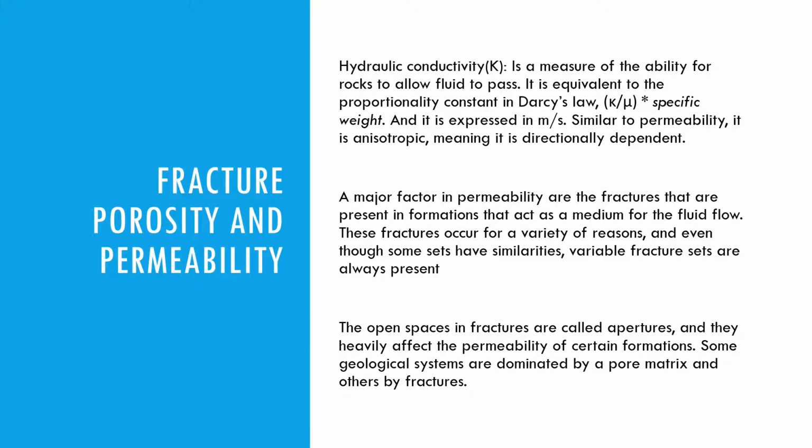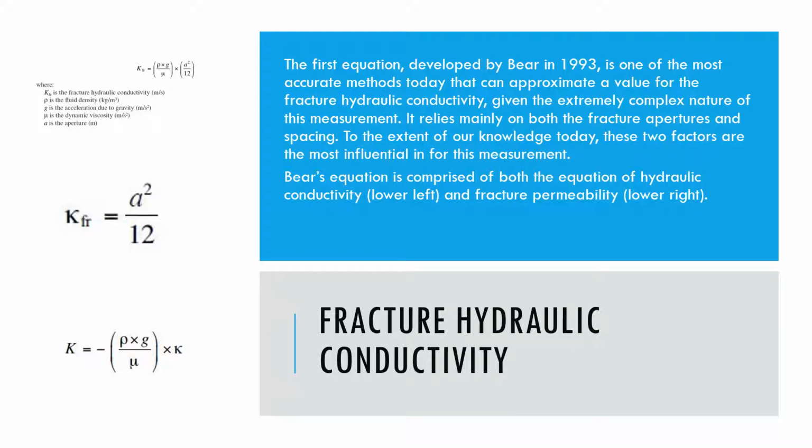The open spaces in fractures are called apertures, and they heavily affect the permeability of certain formations, and by certain formations I mean formations that are fracture dominated rather than matrix dominated. Some geological systems are dominated by a pore matrix and others by fracture porosity, or by fractures in general. Now, we're going to look at equations that have to do with the fracture hydraulic conductivity K.